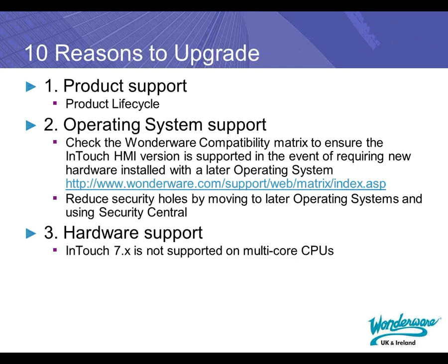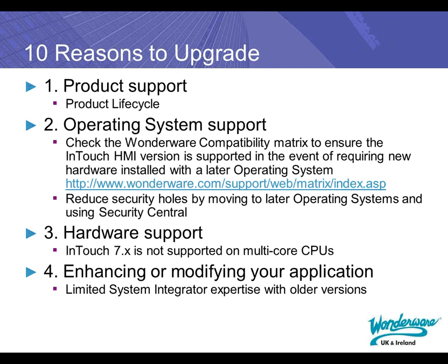Hardware support. Now, in the unlikely event you can obtain an old operating system, there can still be an issue that the older versions of InTouch have never been tested on the latest hardware CPUs. For example, InTouch 7.11 isn't supported on multi-core CPUs. Enhancing or modifying your application. Expertise becomes difficult to find, and system integration may be more costly when changing your application if it's an older version.